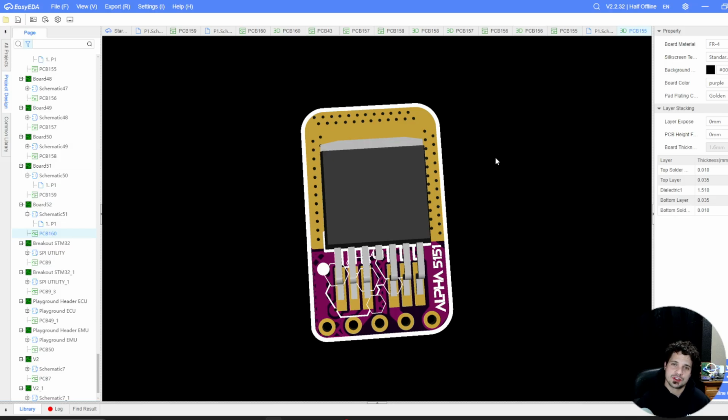The other side of the solenoid, which is the single wire coming off of the top of it, is actually a 12 volt positive connection, and it's waiting for a positive signal from the battery to energize. The reason the ECU can't directly provide that signal is because the ECU works off of low amperage or low controlled signals, i.e. a logic level.